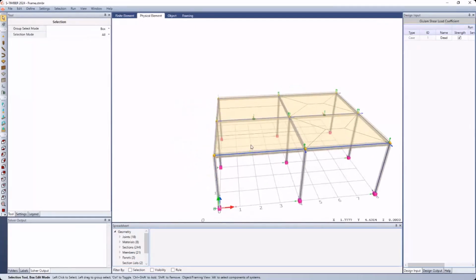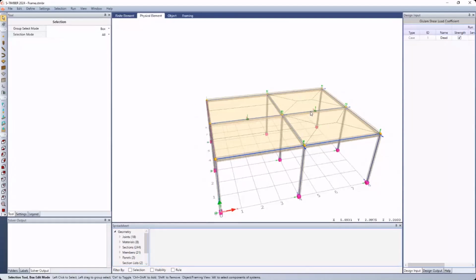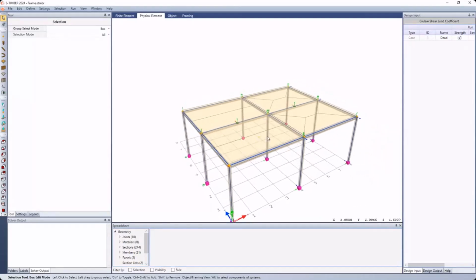for the panels on the left-hand side. So basically, any area loads applied to this panel are going to be shed to this longitudinal member or this longitudinal member. And the same thing on the panel right next to it. But on this other side, we're going to have a two-way span. So basically, any area loads applied to this panel or this panel are going to be shed based off this two-way span definition. So the tributary area of each member is basically shown with these green lines. And the intention here is that I'm going to end up with quite a few different sets of magnitudes of member loads that I'm going to be working with in this example.